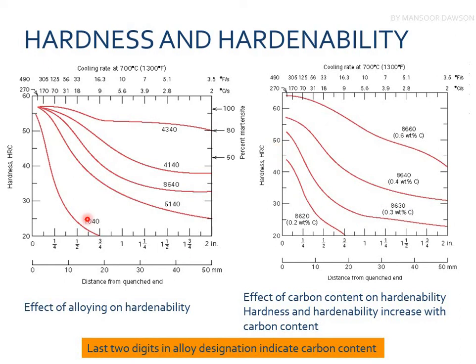Here you can see in the graph that as the distance from the quench end increases, the hardness values decrease. You can check the hardness on the Brinell hardness tester, the Rockwell hardness tester, or the Vickers or Knoop hardness tester, depending.